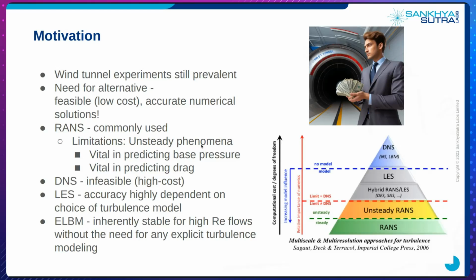So we can always perform DNS, but DNS is infeasible as it's quite expensive. The number of points that have to be employed for a DNS simulation is of the order of the cube of the Reynolds number, which for this particular case would go around 100 to 200 billion points.